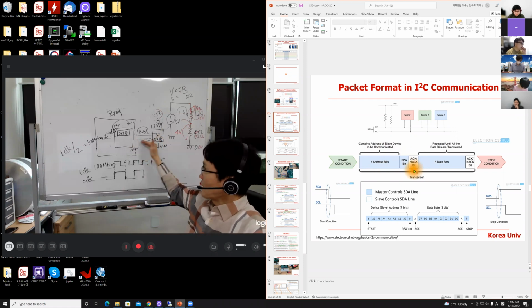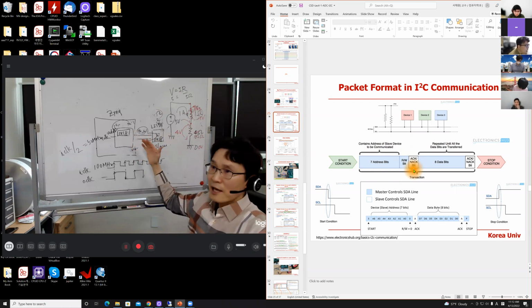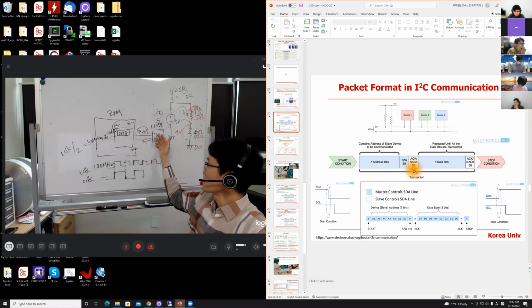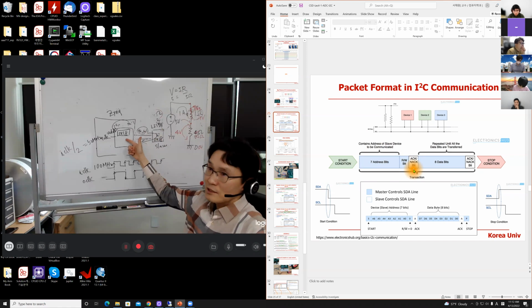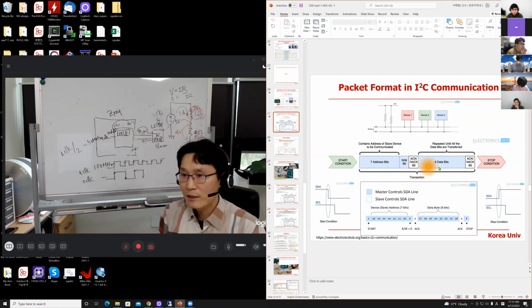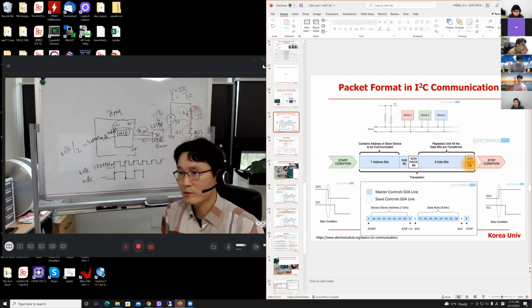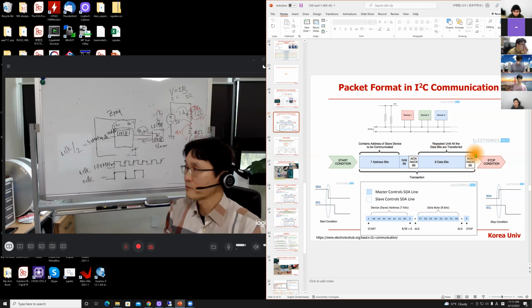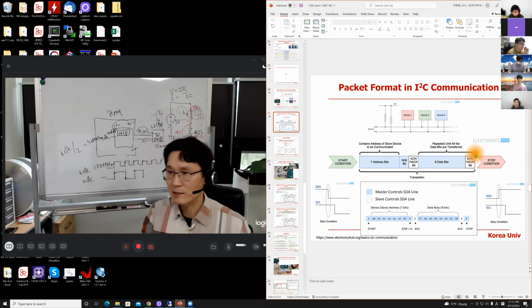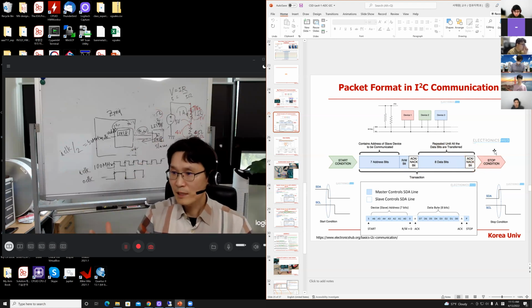Okay, I take your request. Okay, I can take. I acknowledge. So it is like handshaking, right? You are sending something, then okay, it is acknowledging. Then 8-bit data from master. Then acknowledgement, or no acknowledgement if this guy cannot take it. Right? That is the basic format.